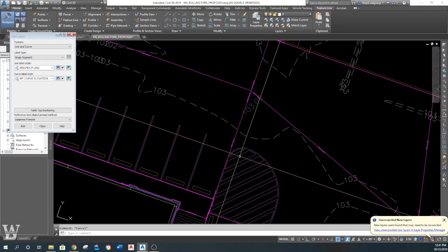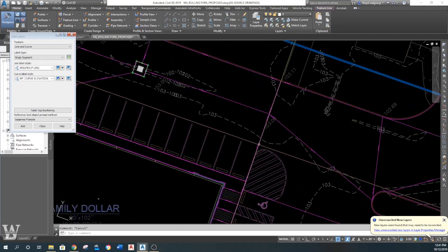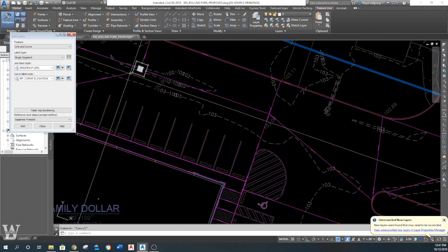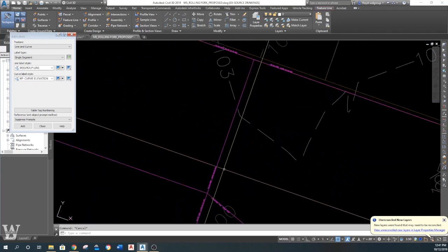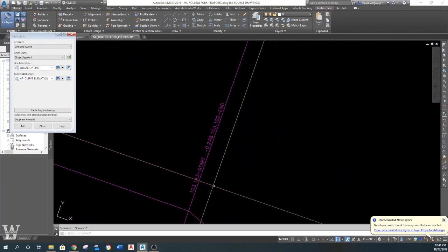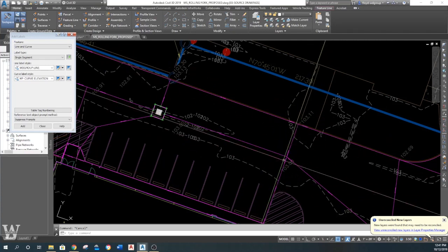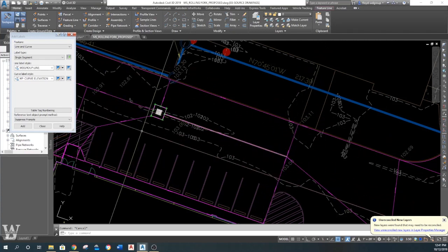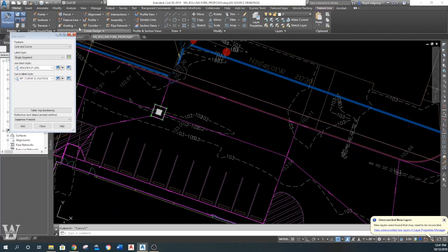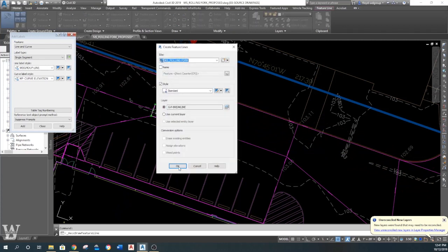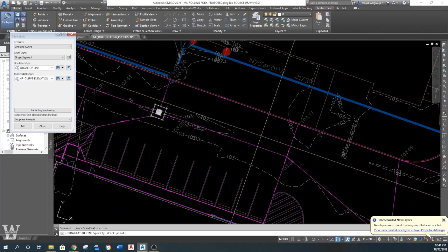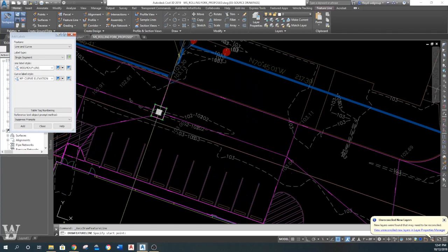That's 9/10. We don't really care what that is. We just need to make sure it doesn't get flat when we come back in here. So 103.1. So it's pretty flat going in that direction. So we've got to slope the water in that way. So what we want to do is, since we know the water's going this way and not that way and down,